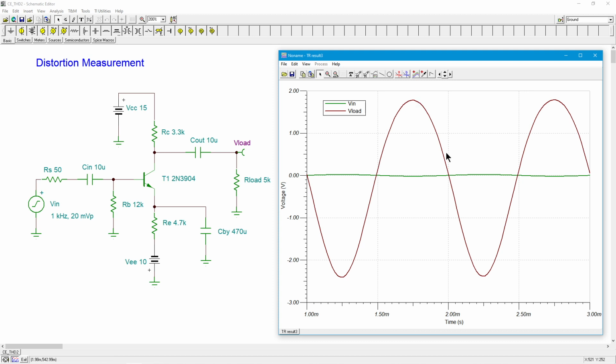If you change the shape of something in the time domain, if you start off with a sine wave and you bend it like we have here, so that the positive and negative peaks don't look the same, you squish the waveform here and elongate it over here, whatever you do, I don't care how you change this thing, if you put a big bump in here or a squiggle over here, whatever it is, if you change it in the time domain, that means you have changed it in the frequency domain. And since we started off with a simple sine wave, which is the basic building block, you don't get anything simpler than a sine wave, that means we've added frequency components. It's that simple. You change the shape, you've added frequency components.